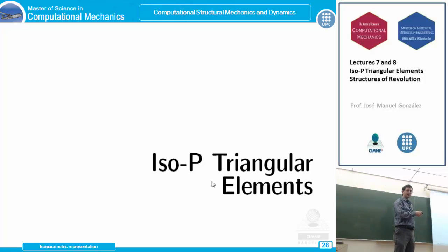First I said that this linear triangle element is a simple element. Just to explain, it's a particular case where we find a closed form expression for the stiffness matrix. So this is very easy to calculate. But if we want to extend these calculations to a much more complex element, we find lots of problems, like the completeness requirement for convergence.